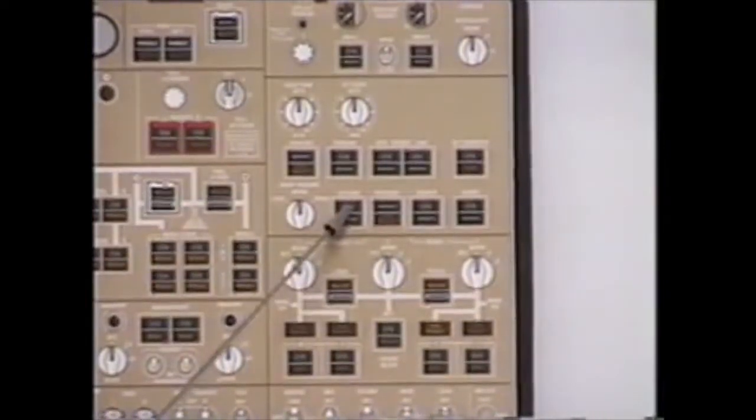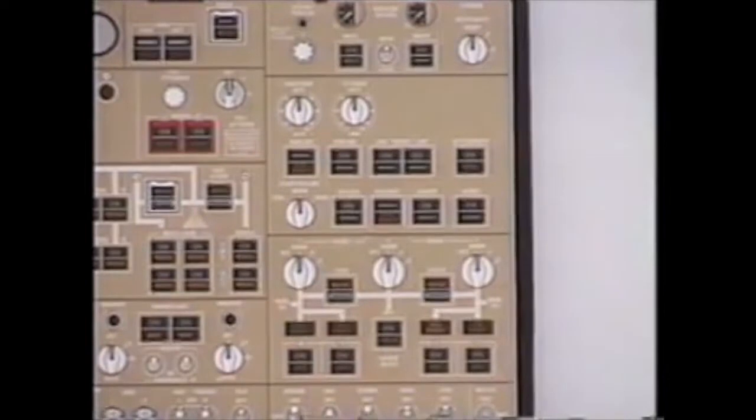High flow: if we press this selection, the packs are in high flow. Humidifier: the flight deck and flight deck crew rest areas only are humidified. No other sections of the airplane are humidified. The humidifier takes water from the potable water system to humidify those areas. The captain will select the humidifier to on during the cockpit setup.